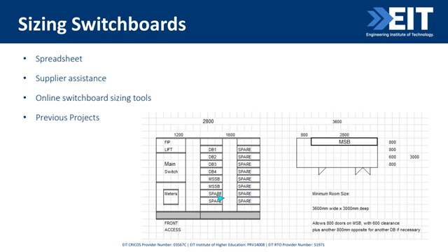On the bottom right here is a little Excel sketch done up for a main switchboard. Typically, your incoming panels could be up to 800 wide, while up to 250 amps, you might have 600 wide tiers. Your cable zones shown here are obviously a lot smaller.